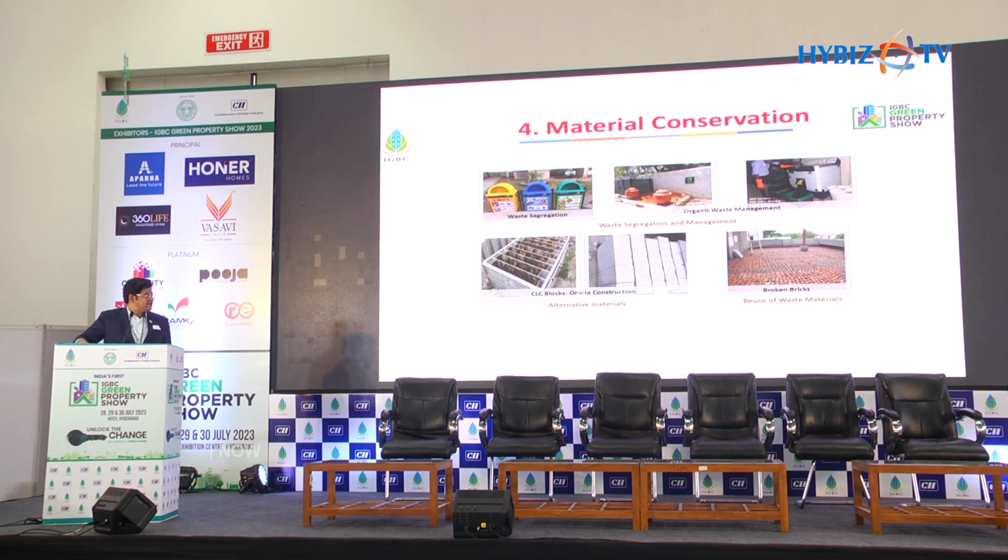That is one thing. The second thing is there's obviously a lot of construction waste that is being generated during construction, right? So if we segregate that waste as and when it happens, for example your AAC blocks can be crushed, powdered, and be remade to use as AAC blocks again and again, whereas scrap steel can also be taken, straightened and used for some other purposes or sold to a scrap vendor who will be able to reuse it. So the main idea behind this is to ensure that the waste material that is generated will not be sent to landfill or some dump yard where it will stay for a longer time. The main idea is to reuse as much as possible. So that is what we have during construction.